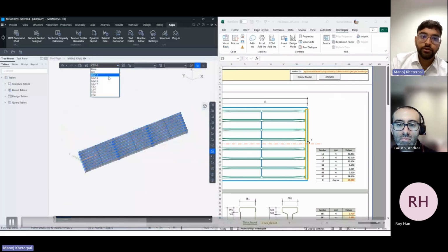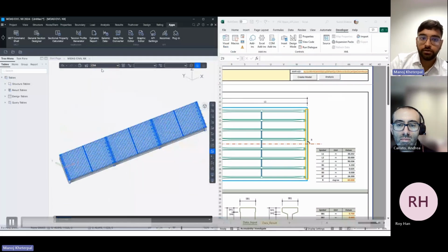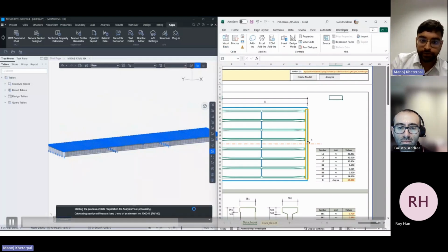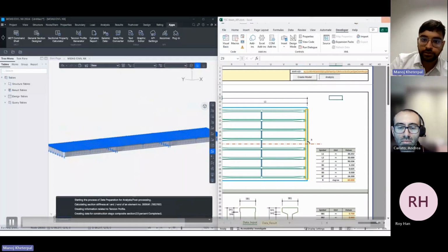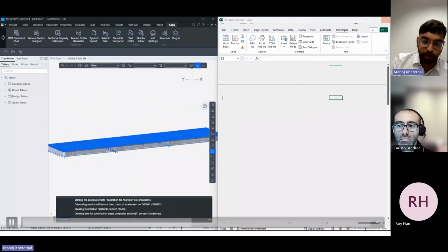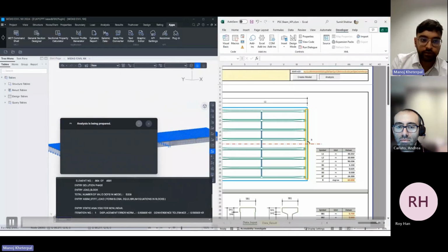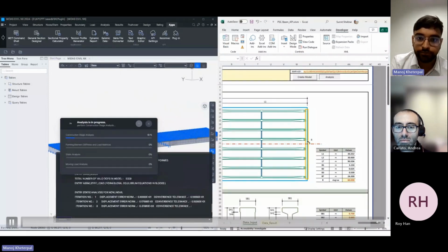And in this VBA example, we defined all the construction stages as well, and everything inside the model, inside the VBA only. Then if you press the analysis button, there is an analysis command that reads for Civil NX. So we can just assign another macro to that, which will execute the analysis command.